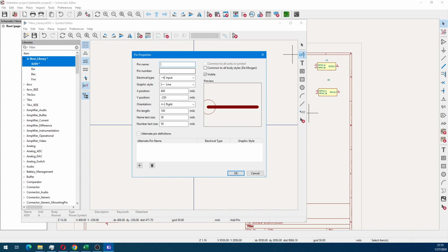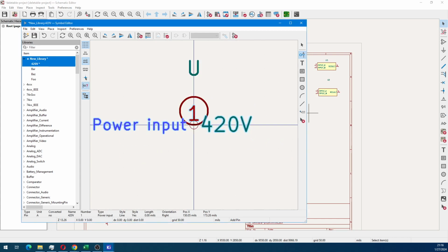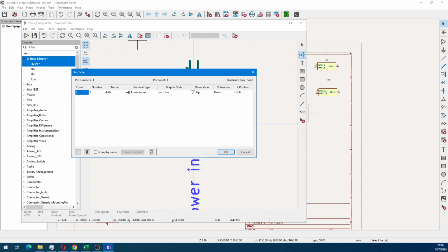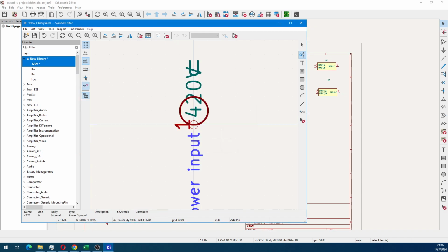So the main thing you want to do is just select power port when you go into that initial dialog creating your custom part, make sure it's checked, and when you go to draw your geometry and place your pins, you want to place one pin, give that pin number 1, make the pin name whatever net name you want to be assigned to any wire that you attach to it. And traditionally, you also want to, and this is where it gets a little bit tricky, I believe you want to make the reference value invisible.